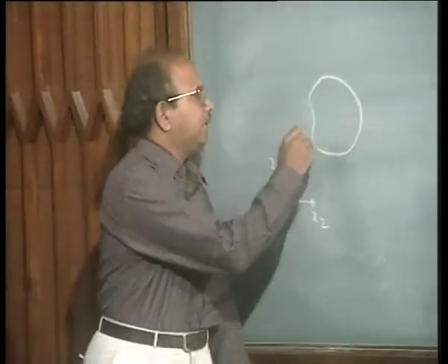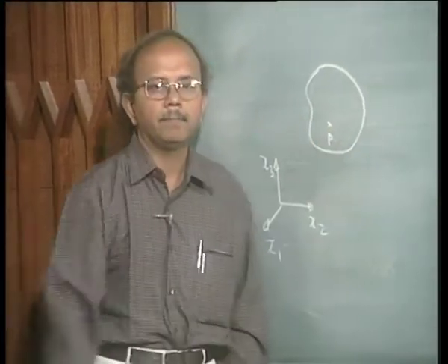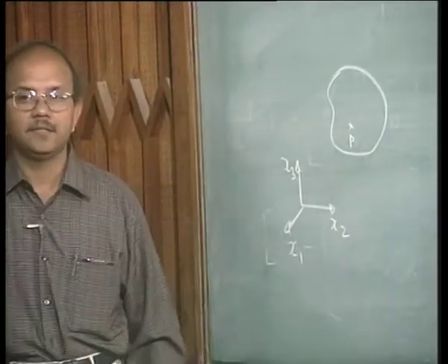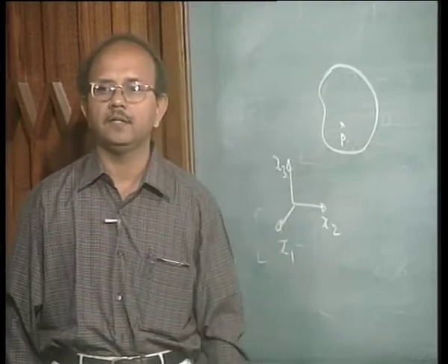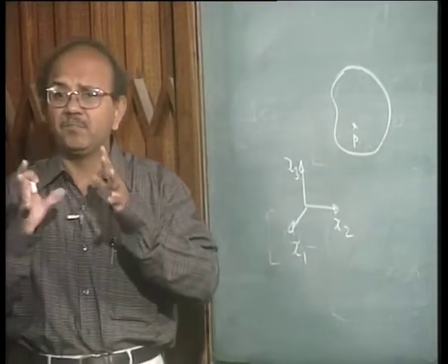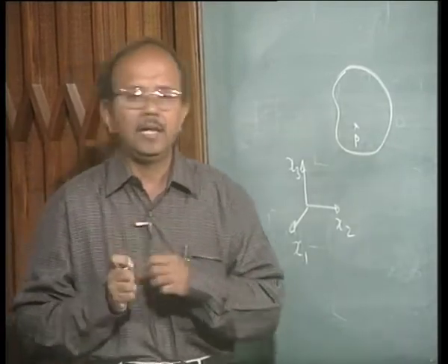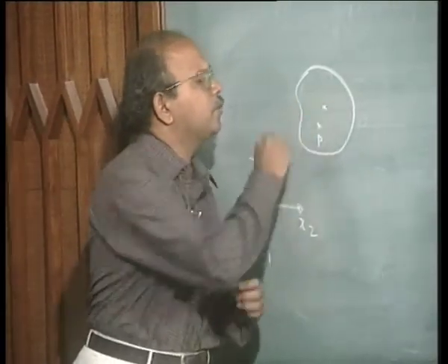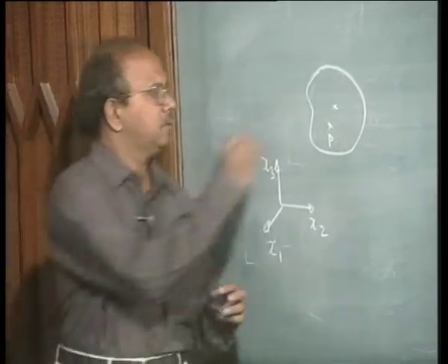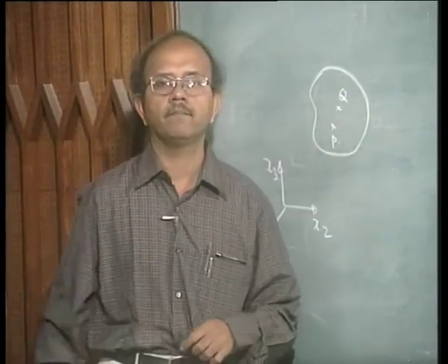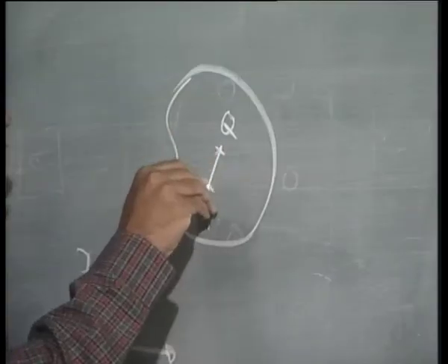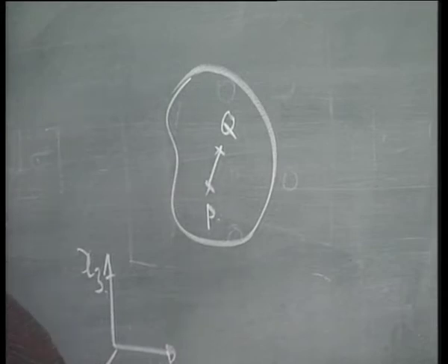Let us say that I am watching this point P, okay, but since our definition of strain just now says that we are interested in change in length by original length, okay, let me take another point Q, okay, which is very close to this P, okay, and look at this line element, okay, which is joined by PQ.